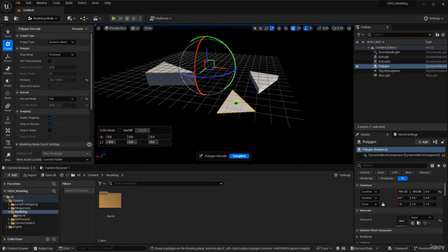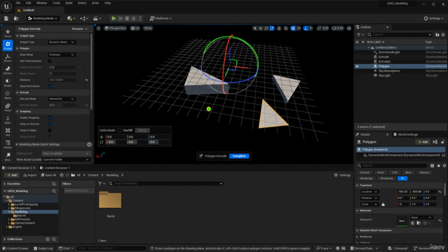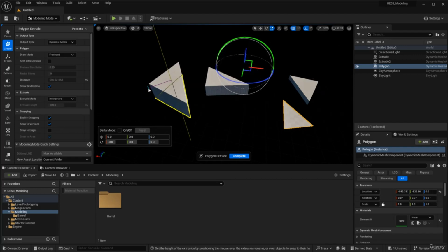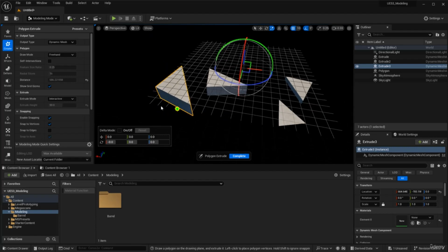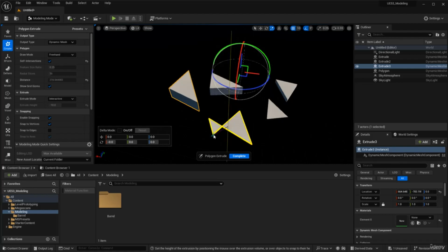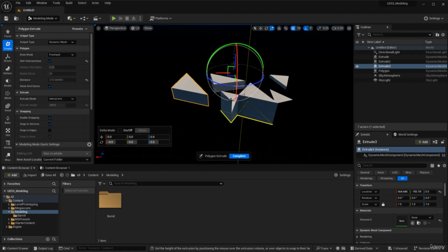After that, you can extrude that. If I go ahead and reset that, if I create again another shape, if I cross the line, as you see, we get a cross point here. So if I click there, Unreal will delete the extra lines for you. If you don't want that, you can click on self intersections, turn it on, and now if I click, as you see, the line is not finished. You need to close it in order to finish the shape, and now you can extrude it.